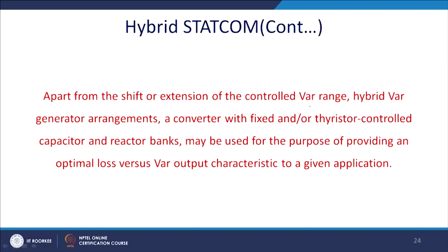Apart from the shift or the extension of the controllable VAR range, a hybrid VAR generator arrangement, a converter with the fixed or the thyristor controlled capacitor or reactor banks, may be used for the purpose of providing an optimal losses versus VAR output characteristic for a given application, because switching losses in this case will be lower. So, we can design optimally what will be the solution for it. Some portion which dynamically changes will be in the Statcom and some portion can be fixed. This is a typical design problem for the FACTS engineers.